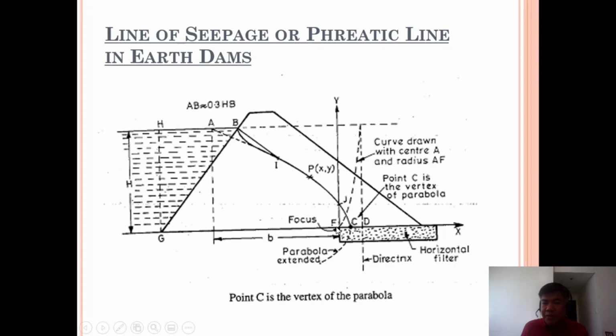parabola. Of course, by geometry you have to determine the focus and the directrix, and you can have now there the F and the D. That is the distance which is equivalent to S, and that is the most important value there, the FD. You just multiply it with your permeability, and that's it, you have the value of your Q. Again, although there is an empirical formula given, the process of finding the FD is still graphical.